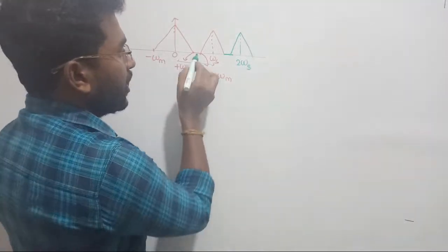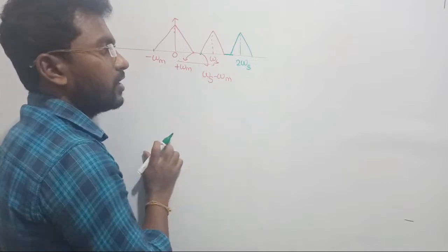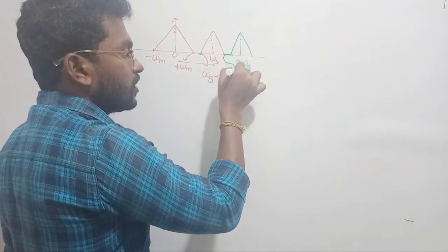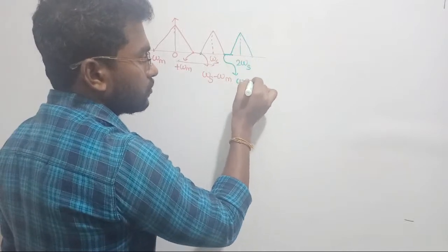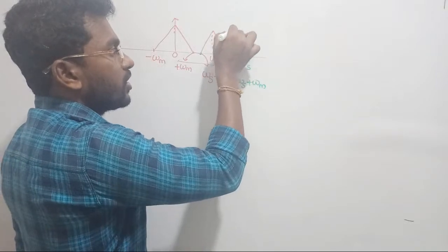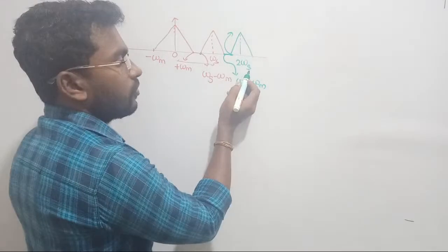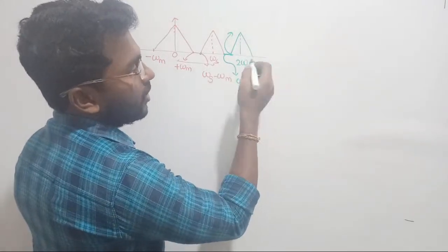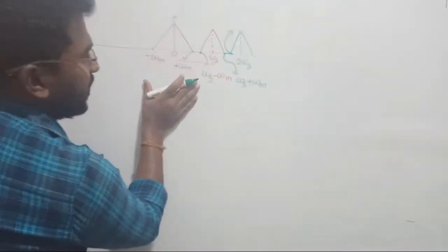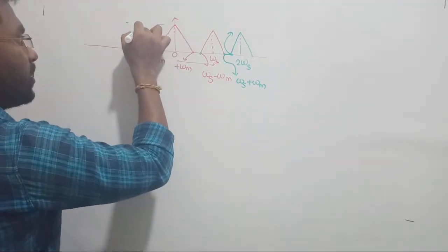So for the next one, we are maintaining this value, and the value we create is omega s minus omega m. Then you can continue, right? On the opposite side here we get omega s plus omega m. Similarly, this is going to be omega s, and we consider twice of omega s, right? Again twice of omega s minus omega m, and oppositely twice of omega s plus omega m. That process keeps continuing, and you can do the same thing on the left hand side also, right?